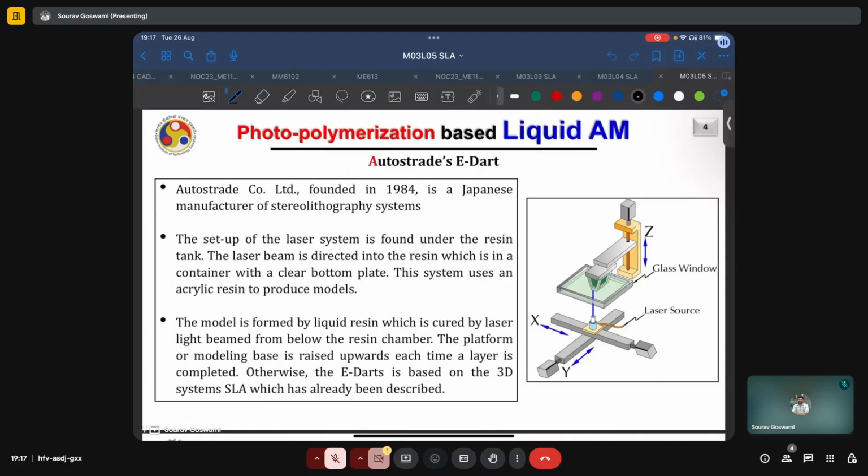Also, now since the resin or the vat of liquid is not moving, any surface perturbations or surface waves in the liquid are minimized. But the downside is that because of the X and Y motion of the laser source, it is not a very fast process, because we cannot move those optics at great speeds.